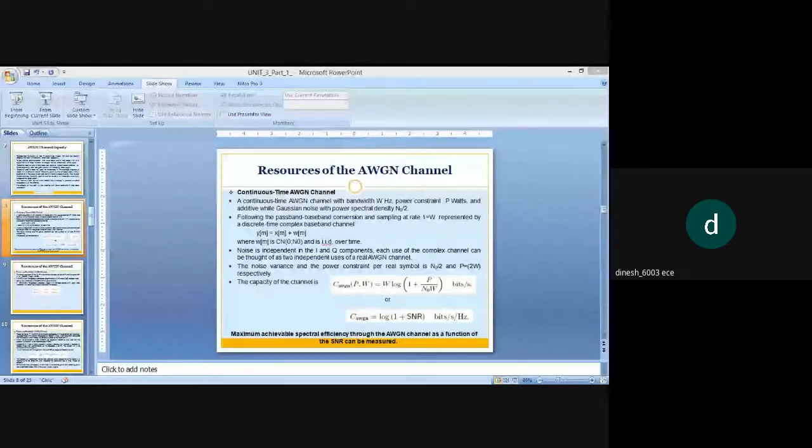In fact, it can be directly calculated that the capacity is increasing and concave in the bandwidth W. If the bandwidth is smaller, the SNR per degree of freedom is high, and then the capacity is insensitive to small changes in signal to noise ratio. If the bandwidth is larger, such that the signal to noise ratio per degree of freedom is small, the capacity is proportional to the total received power across the entire band, and it is insensitive to the bandwidth, and increasing the bandwidth will have a small impact on capacity.